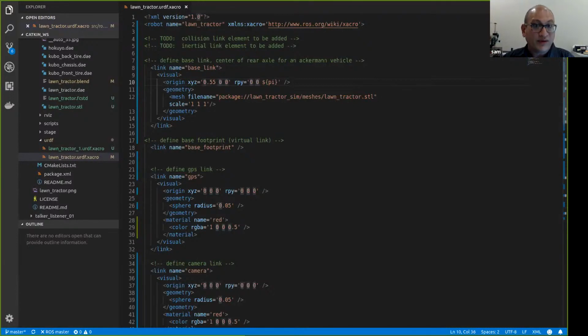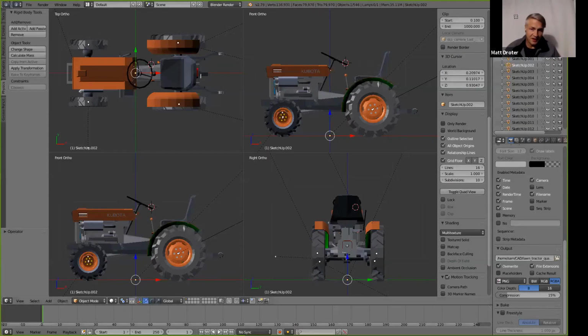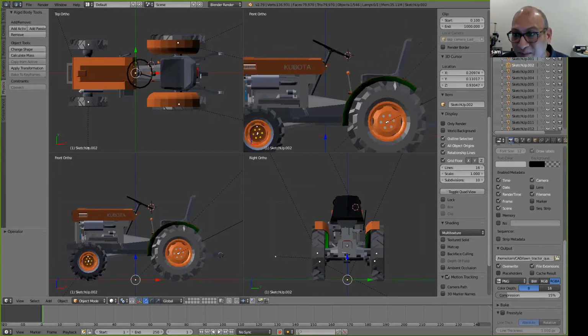But we're still not at the origin. So we're going to take care of the XYZ part now. Let me show you again. I'll stop sharing this and I'll share the other screen. So there's a difference between the base link origin and this image origin, and that's what you have to measure. And that is what I'm measuring when I said 0.55. I actually was coming towards this point, and this point's far out in the X direction, 0.57.